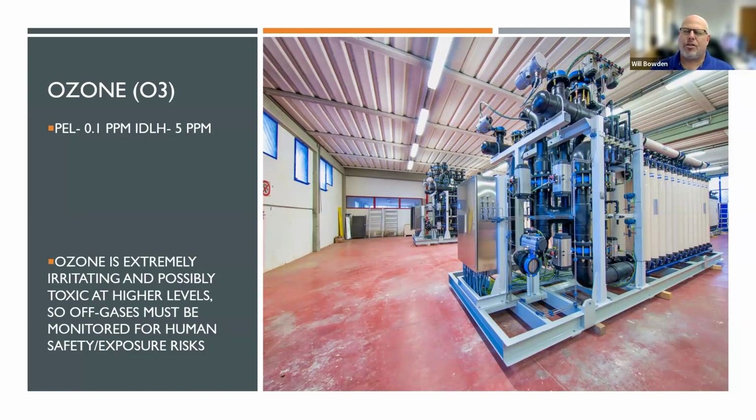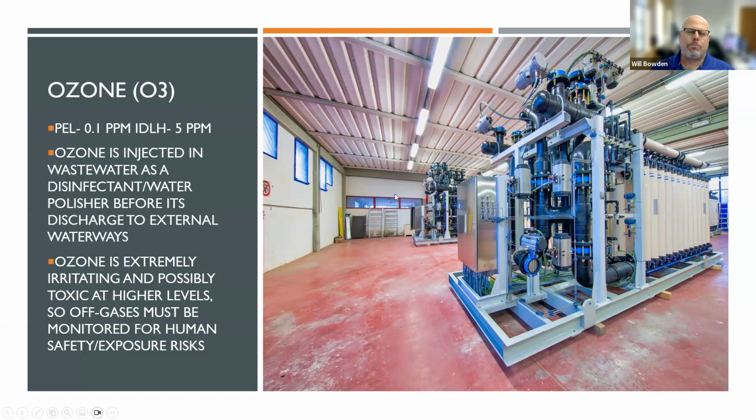The IDLH is 5 ppm. And in wastewater applications, ozone can be injected in wastewater as a disinfectant or a water polisher before it's discharged to external waterways. The potential situations and danger of ozone is that it is extremely irritating and possibly toxic at higher levels.